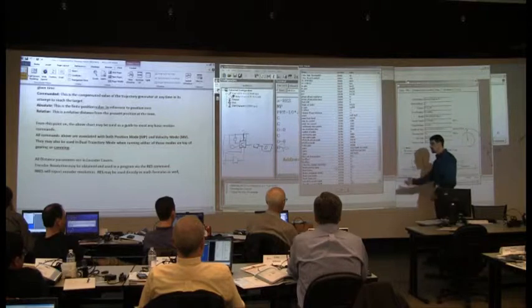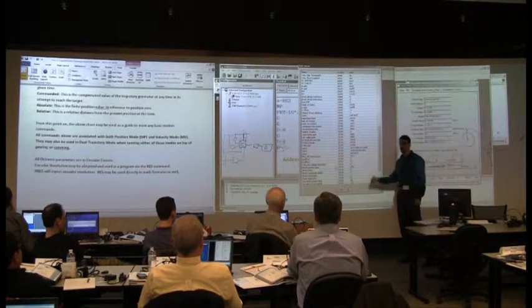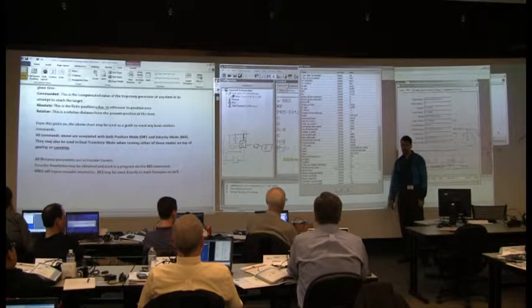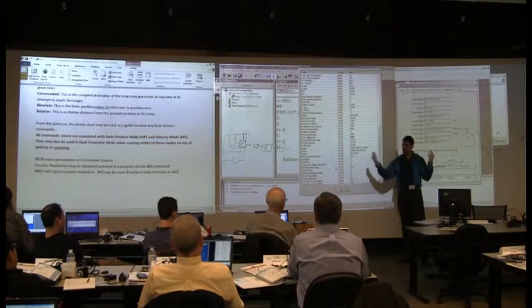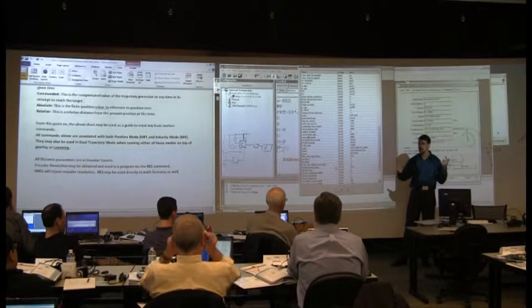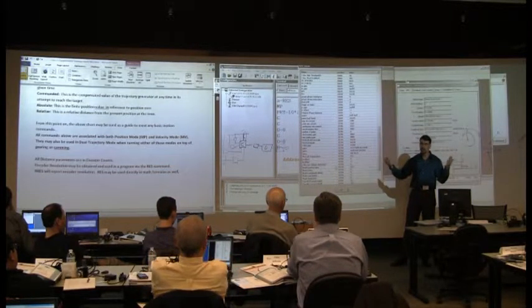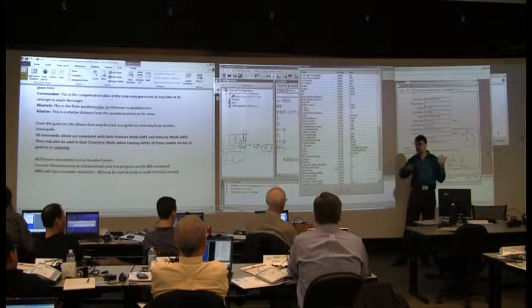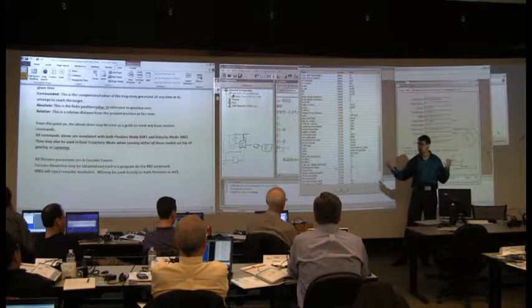It may not be going that fast, but in reality, back EMF is what limits peak current through a winding. Some people will say, no, it's the way you run your drive. Well, yeah, we're talking about the motor itself. If we have 48 volts on a bus, and we have a 1 ohm winding in a motor, and we turn on the switch to turn on this phase, it's going to get 48 amps, period. That's the laws of physics. How fast it gets to 48 amps is another question.